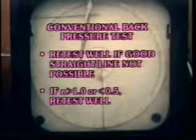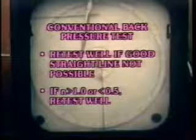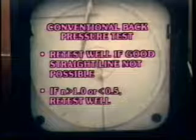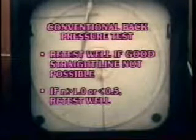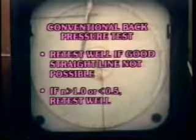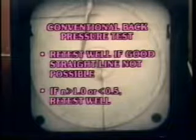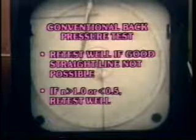If the same condition exists upon retest, then specific values of N equals 1 or N equals 0.5 are used, and a straight line is drawn through the highest flow rate point in the former case, that is, for N equal to 1, and the lowest flow rate point in the latter case, that is, for N equals 0.5. Because of the potential need for a retest, it is important to make preliminary calculations at the well site before the testing contractor is released.